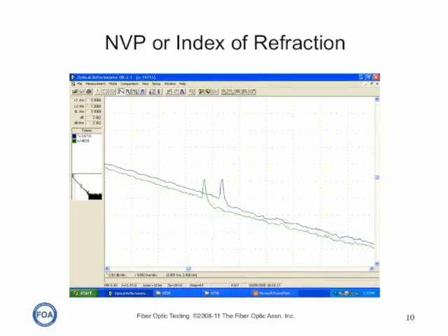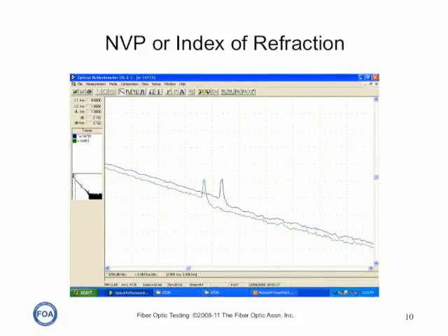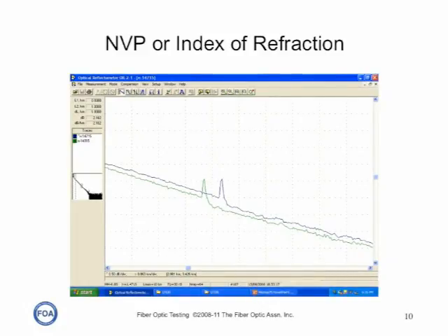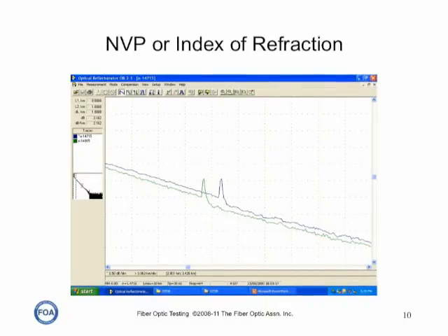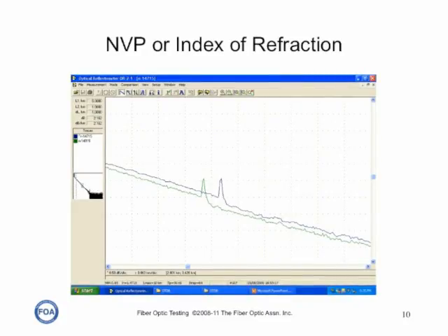Sometimes we just have to set an average because we're looking at a long cable plant that has numerous fibers spliced together that may be different. So this induces an error that we sometimes can compensate for and sometimes we can't. But it also affects the length measurement, and we need to understand it as well as possible. If you don't know particularly what it is, set the value to an average.